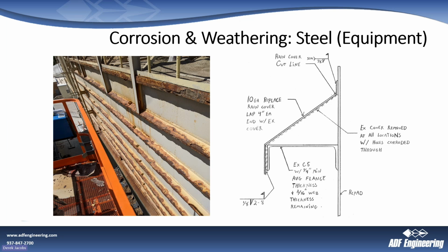It was very thin metal, 10 gauge metal. And unfortunately, once that happened, then it became a pocket where all of this material and water sat in here and then started eating out the actual stiffeners, these 5-inch channel stiffeners that were part of this too.